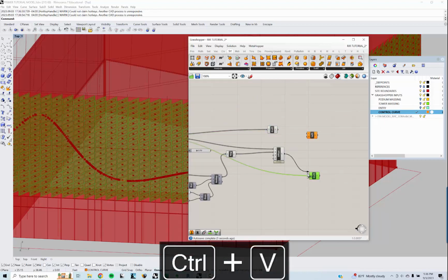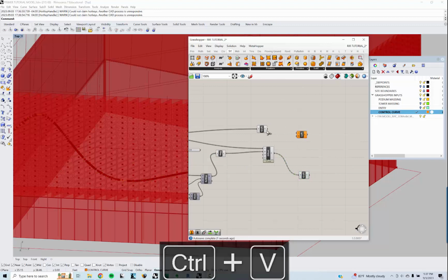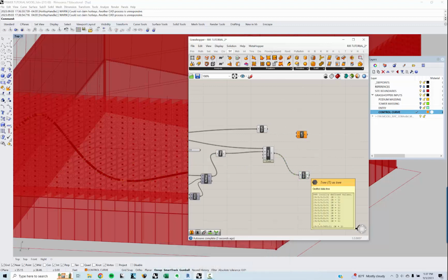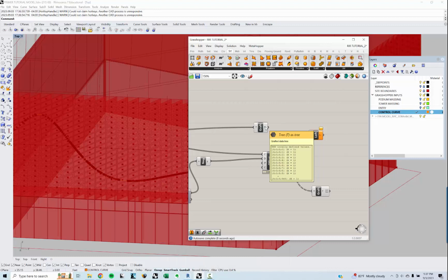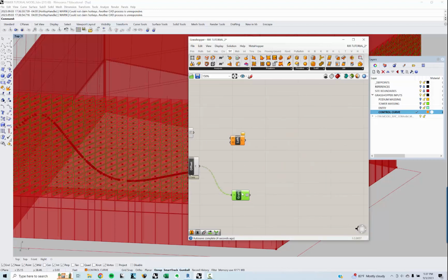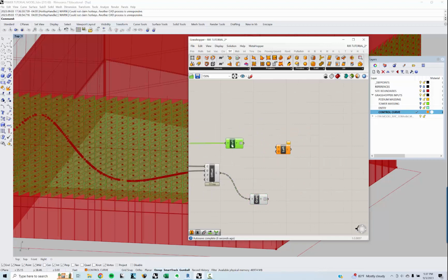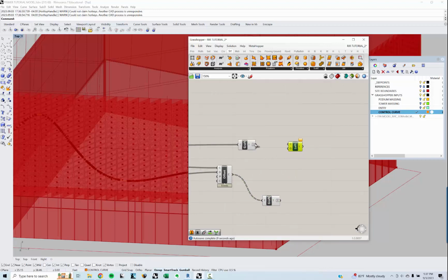Graft this list. And now I'm going to simplify this list, because let me show you what that does. This has a whole bunch of branches that are empty, or it's got zeros, so it's splitting it way too much, more complex than it needs to be. Simplifying it removes all those zeros and all of those layers of branching that are actually not really changing anything.